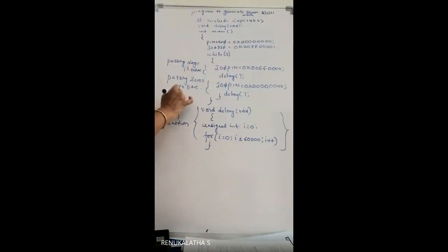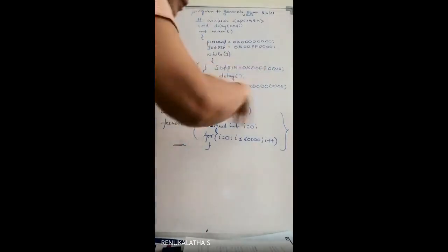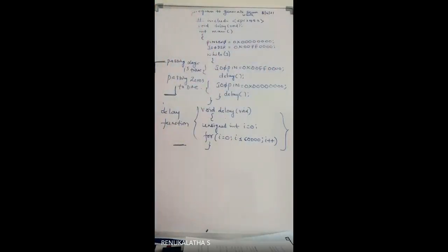Logic ones are sent to the DAC and it will generate this part of the waveform, the high level. And this generates the lower region, the 0 level. This is the 1 level. The upper part of the waveform is created by this part and the lower part is created by this one. If you join them, it will be in a loop unless you stop, and then it will generate a square waveform.